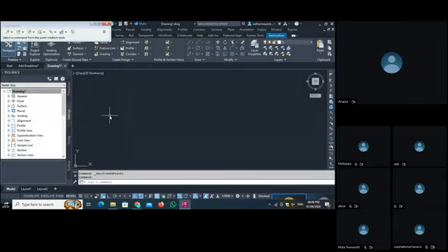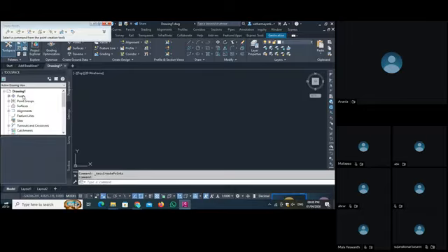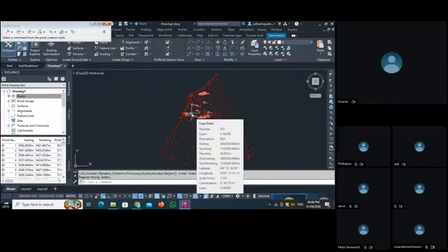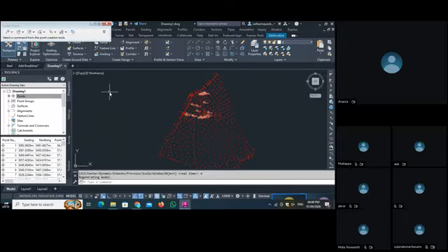As you set OK, you go to the Prospector tab. Click here on Points, and you can see your points are imported now, but the points are not seen on our screen. To show the points on our screen, we have to type Z, enter, E, enter, E for elephant. Okay, so now the points are shown here. So this is the simplest way to import your points. I hope now you understand the flow.